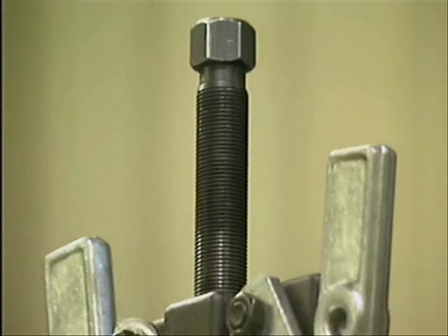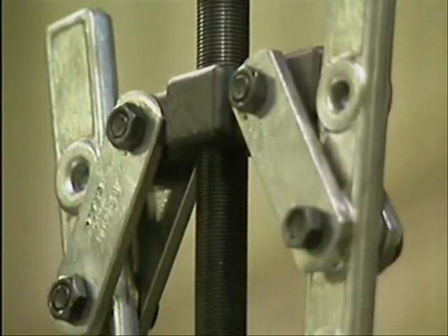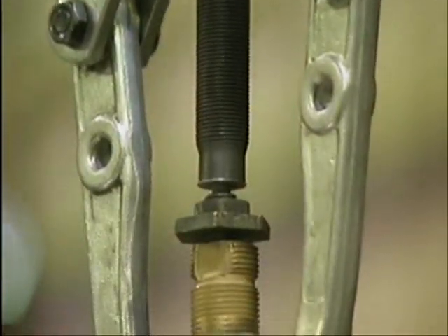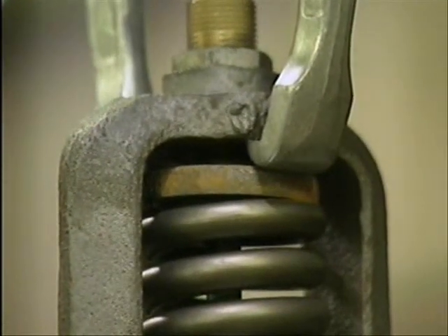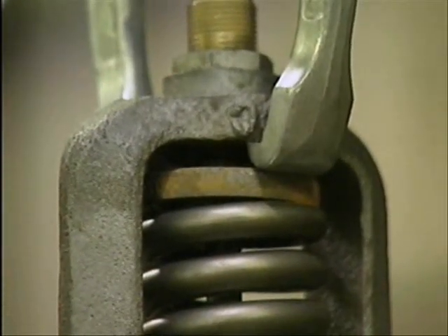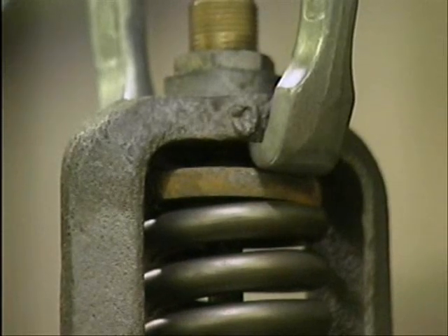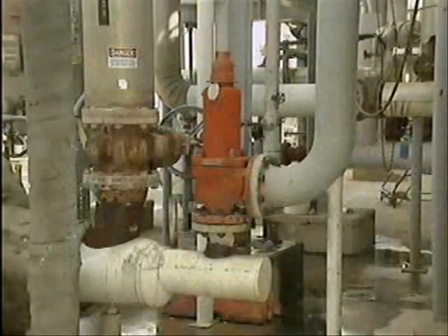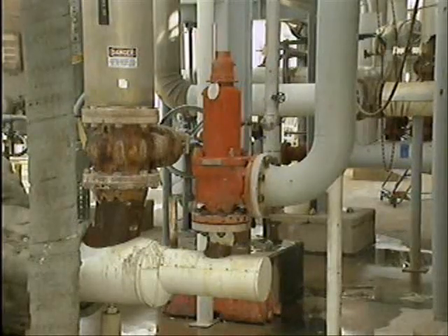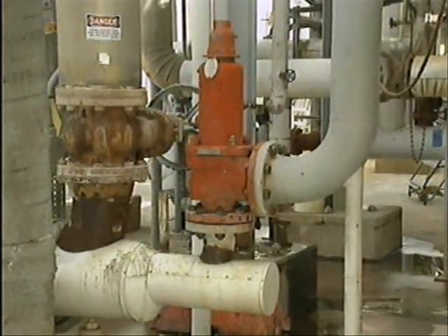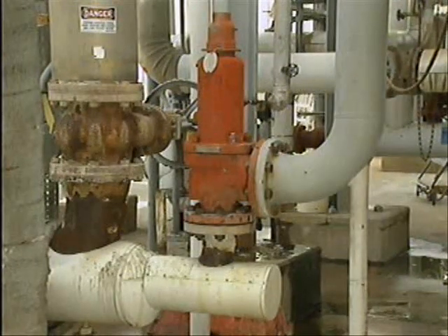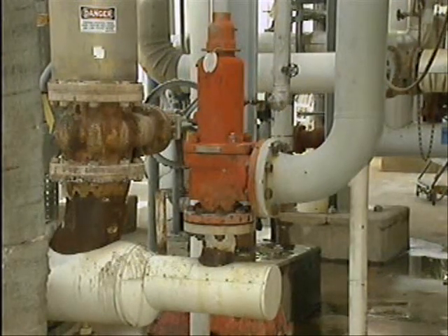Gagging a valve improperly can be disastrous. Damaged valve parts or serious injuries can result if a gag were to slip and the valve open unexpectedly. So it pays to keep in mind some basic safety tips about gagging. Never apply a gag to a cold valve that will be heated. The valve stem expands considerably as temperature increases, and if the stem isn't free to expand, it will be bent.